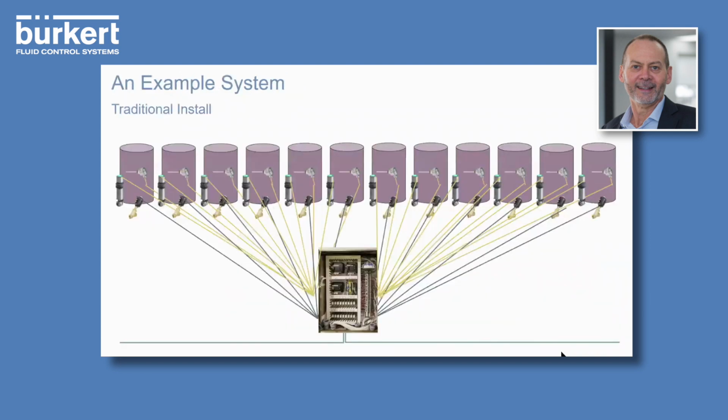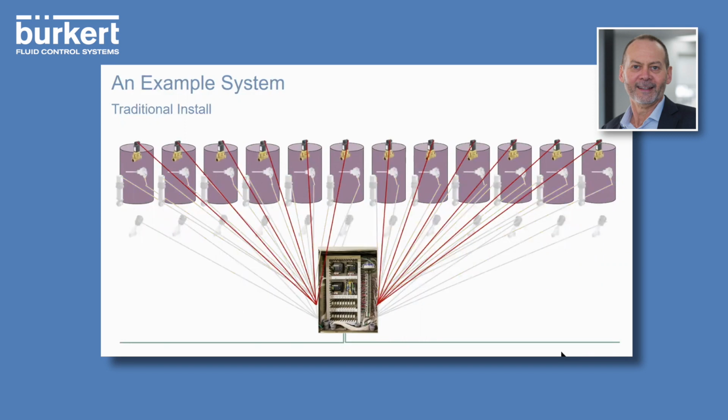But projects don't always go as planned. Let's just say on our application here, the winemaker comes along and says, I want to add tank blanketing. So I want to add a solenoid valve per tank. So something as simple as a solenoid valve, now we have to consider, did we allow for that in our initial panel design? In other words, do we have enough outputs? Do we have enough terminals? Do we have enough size? Do we have enough room? Looking at the panel we're using here, the answer would probably be no. So you may even need a second panel to be built.